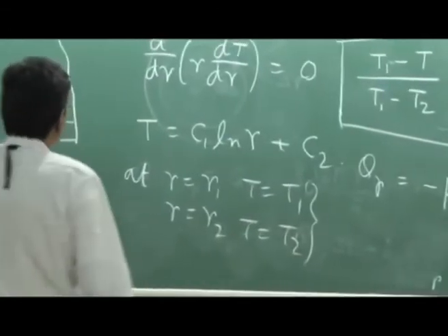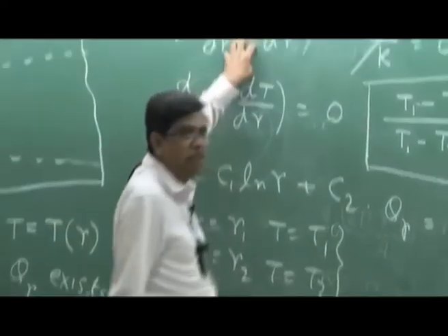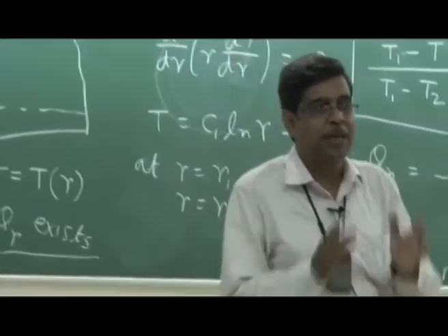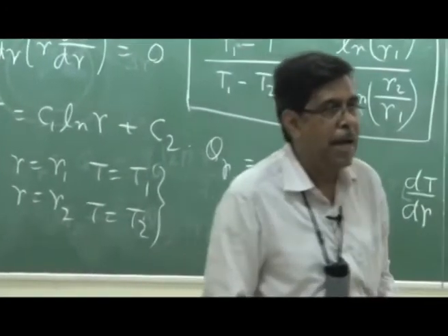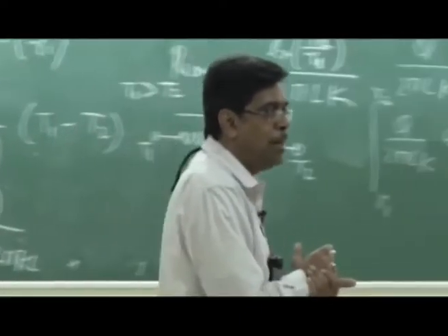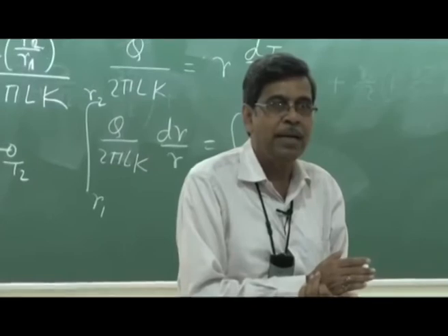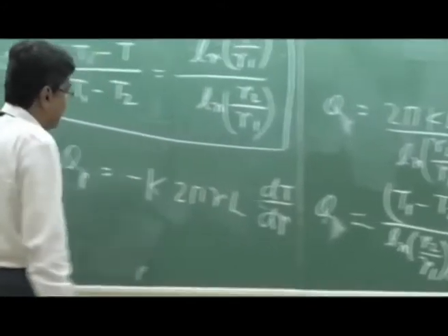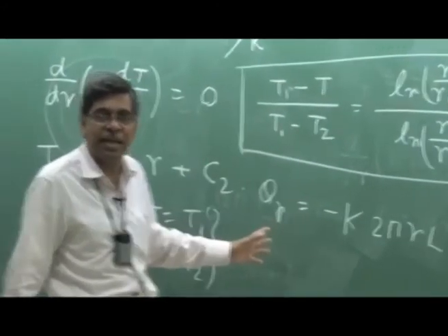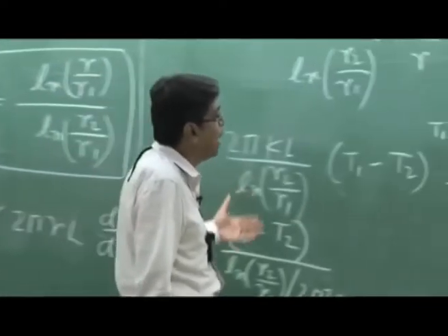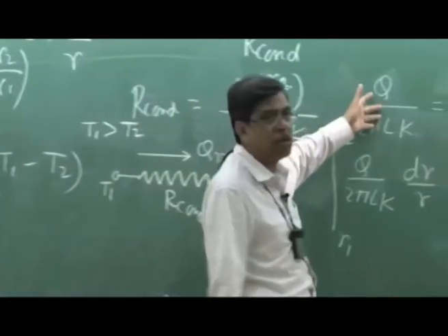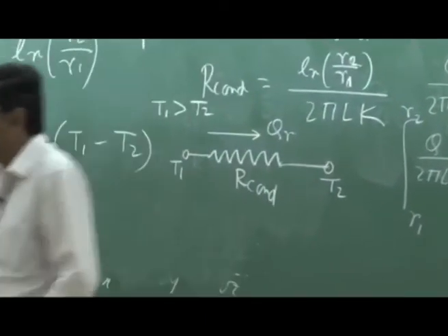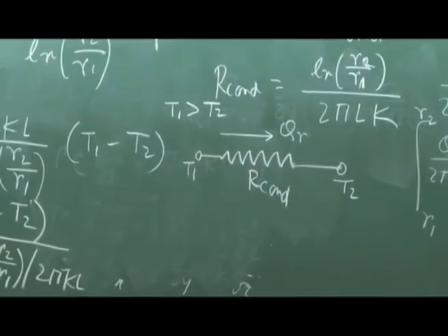But it is always better to derive an equation, because under certain special or complicated cases, you must have this practice of generating the basic equation from an energy balance over a small element of the heat conducting medium. This is always good, so that you arrive at and solve the temperature distribution and then write the Fourier heat conduction equation. And this is one of the easiest ways most books write, taking Q to be constant across all sections. That's all.